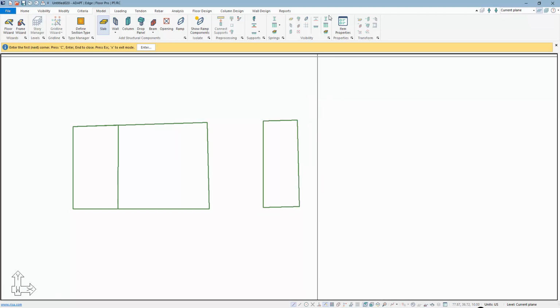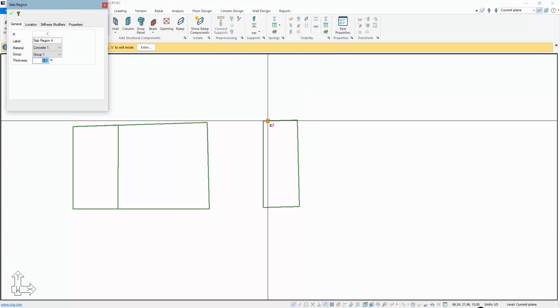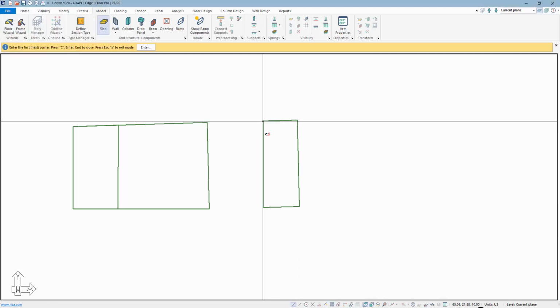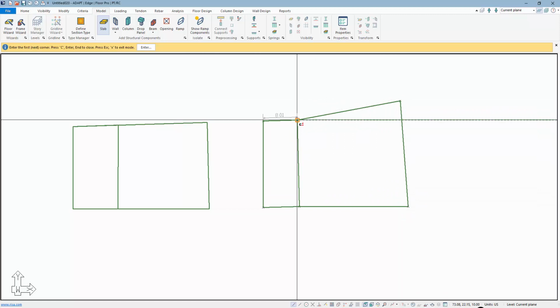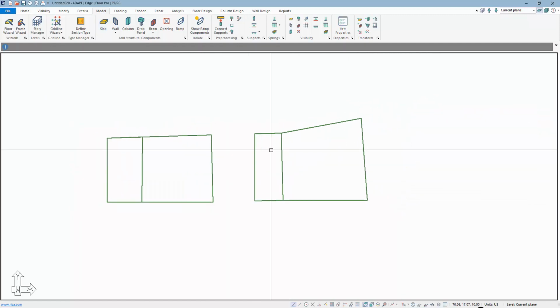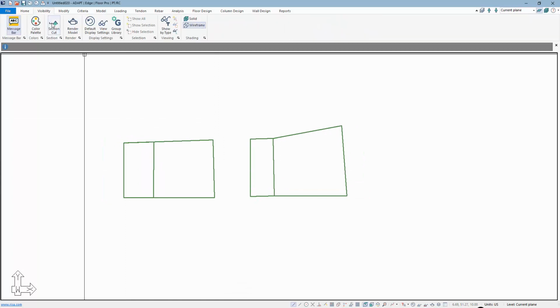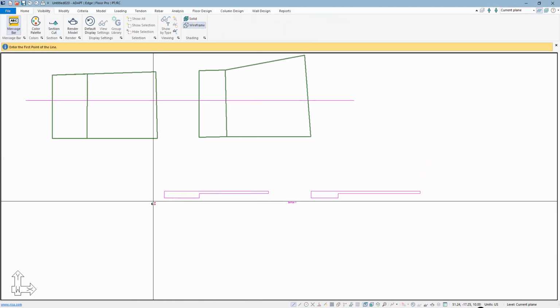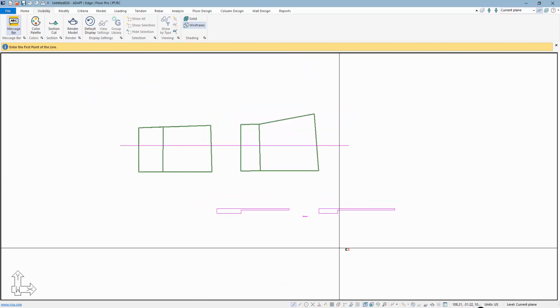And now if I go back and say, well, I also need to draw an 8-inch slab, we're going to do that. And we'll draw in an 8-inch slab here. So we're going to draw this slab. Let's just draw like so. Okay, so we have two slabs that are essentially the same in terms of their geometry. If I take a section cut from the visibility tab, we can see there's this 24-inch step here, or I guess a 24-inch thickening, and then we have an 8-inch slab.